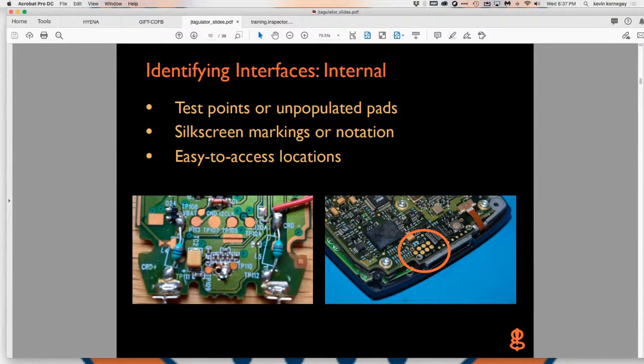Although you may see a pad, and that's a good indicator, or test pins or test pads, such as here on the left or here on the right. Look at all these chips, it's hard to access, but you're really searching for this test access port called the TAP, this 4-pin port. You just look for anywhere where you see some grouping of pads like this, okay?